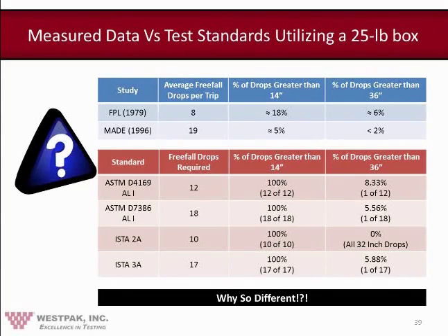At this point, you might ask yourself, why are we beating up our packages so much? The reason is that when you're testing a package, you definitely want to always test for the worst case. You don't want to have damage on that 1% or 5% of shipments, because damage, you could say, is not good. And we definitely want to cover all our bases, to say the least. So that's for drop testing.